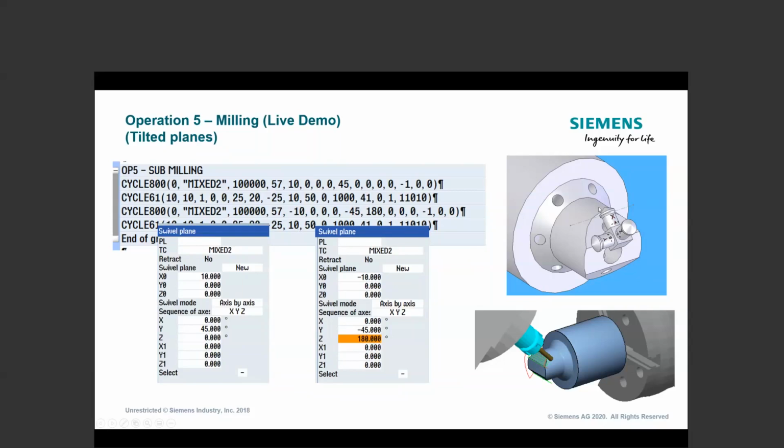These final positions here in the cycle would be if I then wanted to shift my 0 along the new inclined plane. If you guys want to get into more description on cycle 800, I did do a milling cycle 800 video, two different ones, one for ShopMill and one for G-code, where we really dig into this even deeper as far as each of these variable types.